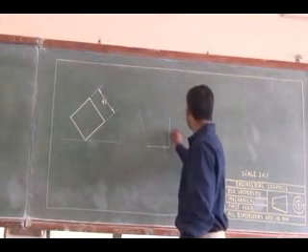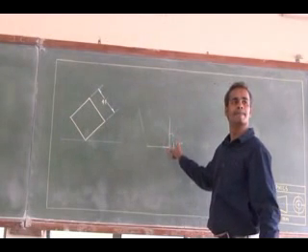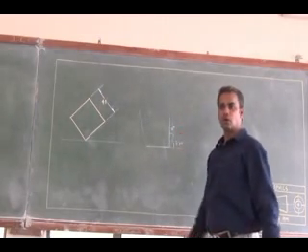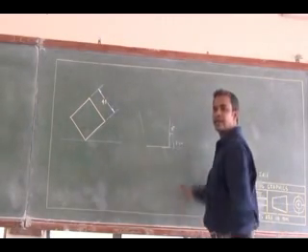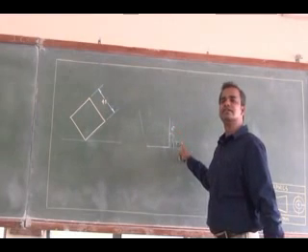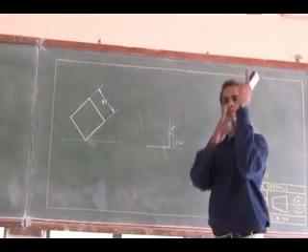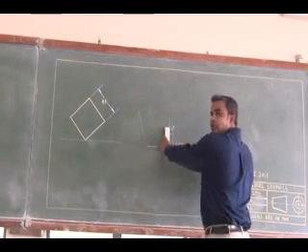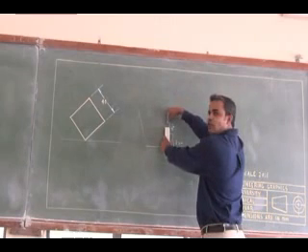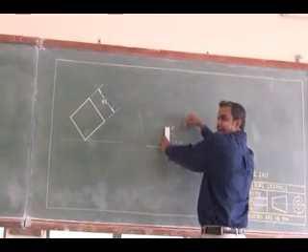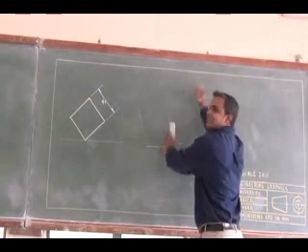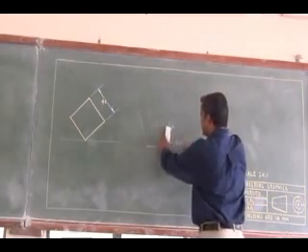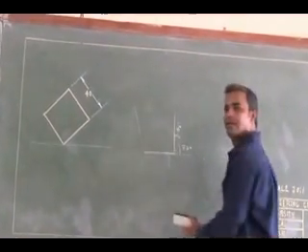Can you tell me what will be this angle? 90 minus 72 will be 18 degrees. Right. So to draw this line, either I can use 18 degrees or 72 degrees. So I will have my drafter perfectly 90 degrees, 2 scales perfectly 90 degrees. I can have my drafter here. Either I can move this vertical scale of my drafter to 18 degrees, or my horizontal scale to 72 degrees. This is convenient for you, you can use it. Right. So once you have set to 18 degrees, using that scale I can draw my other side.